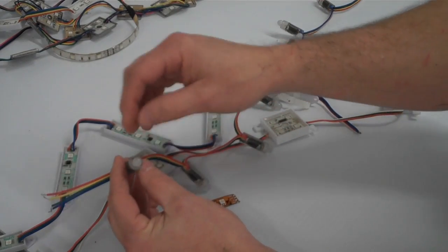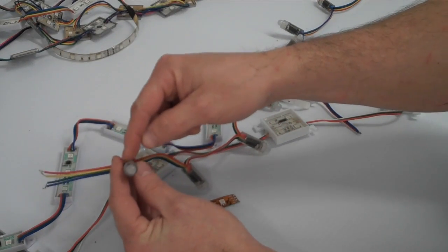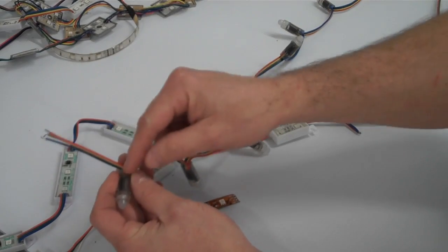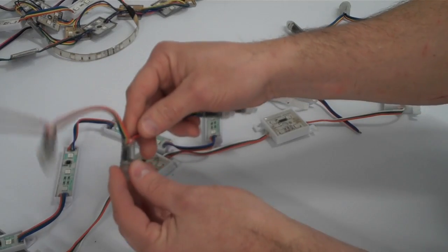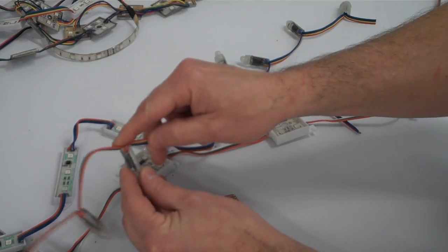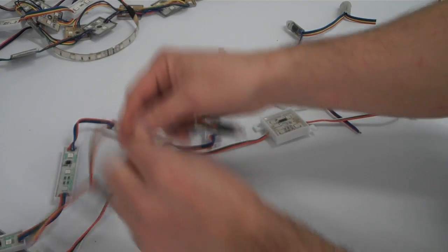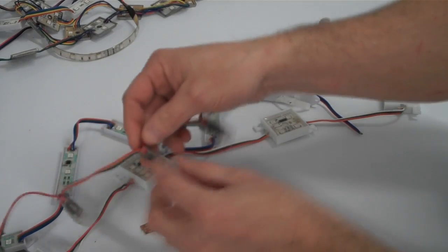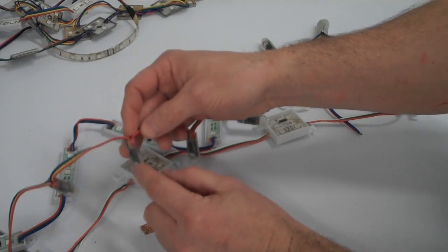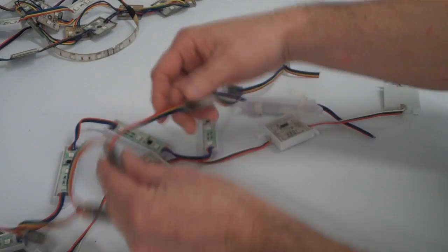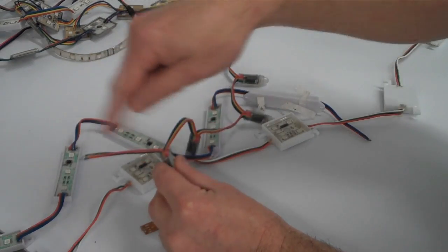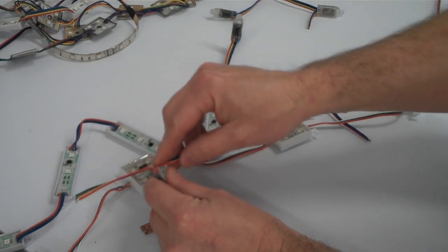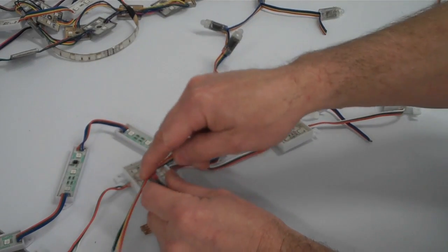The first one, this node here, or this pixel here, will take the first brick off and say, that's my data. This particular pixel then thinks it's the first one. It takes off the first chunk of data, then sends it down the line to the next pixel. This pixel takes off its piece, and so on. So the distance from the start of the controller is what determines the order of these pixels.